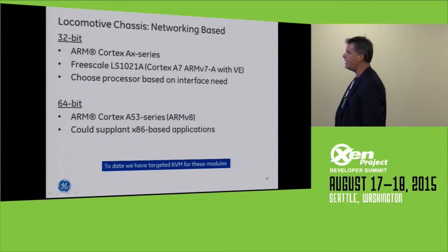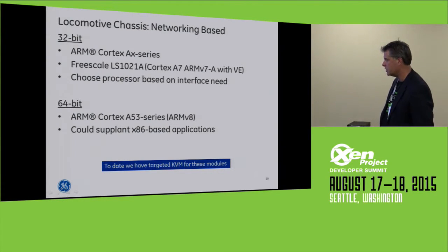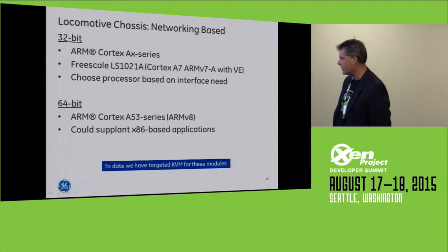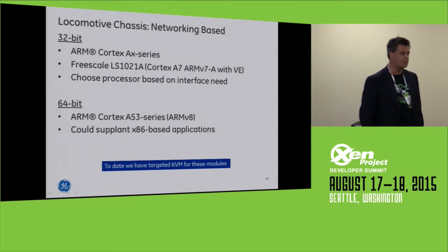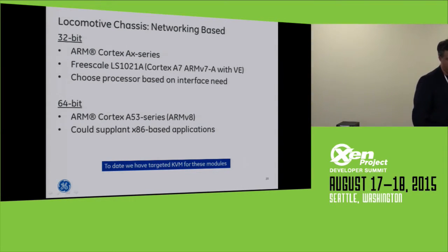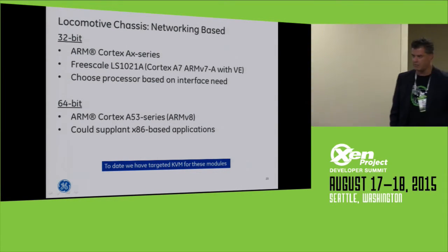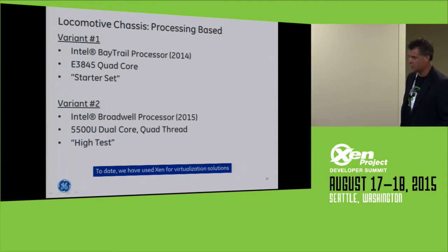64-bit, we are looking at that. Right now, they're a little bit too high power for us, too much heat for us to shed. And I will tell you, it's kind of the cliff note down there at the bottom, we've run into some issues with Xen on ARM, especially with the Layerscape 1021 part. Right now, we're using KVM for that particular processor card. I'd be more than welcome to talk with anybody about that to see if we can fix that, because I hate supporting both.